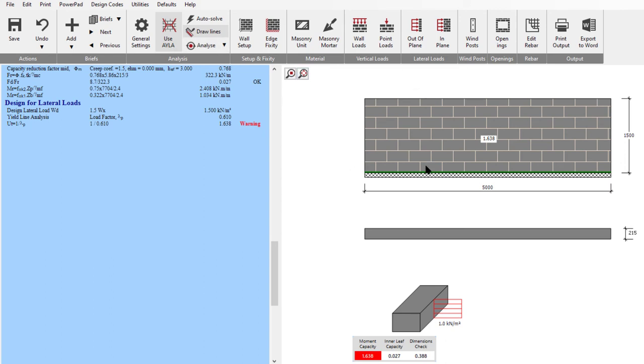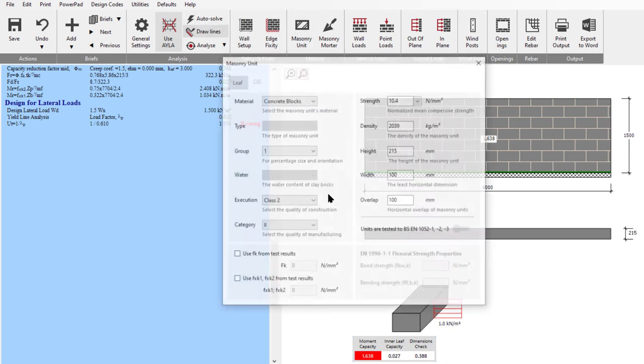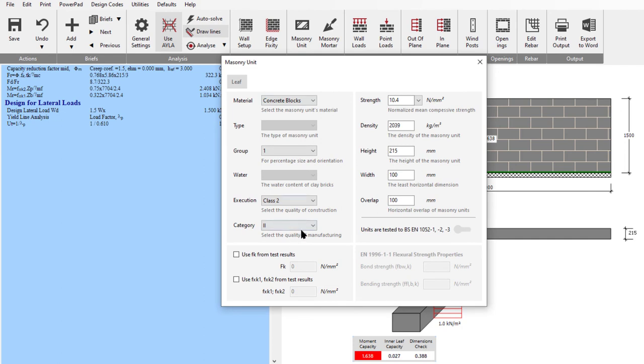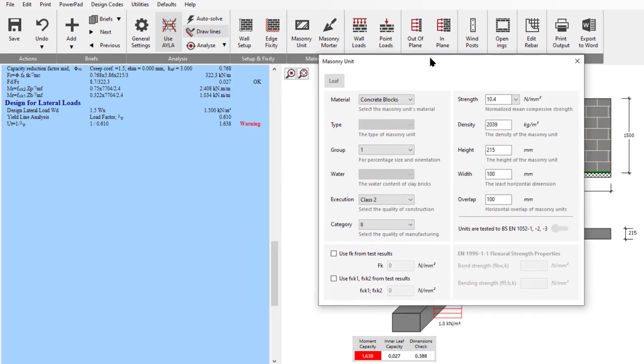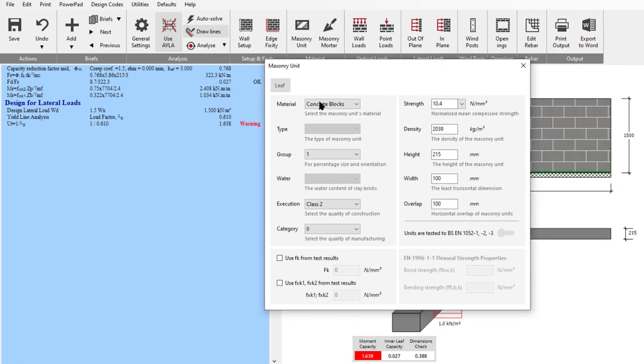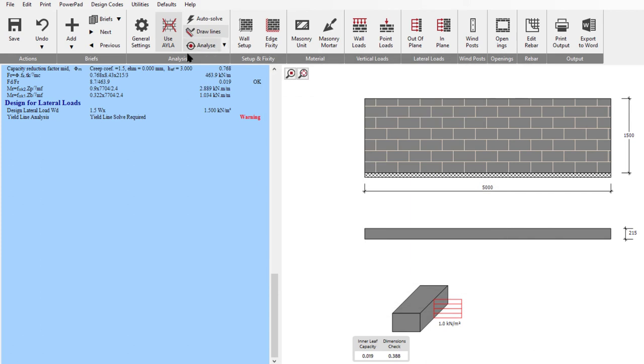What we can do is we can introduce piers, or we can thicken it. We can also, to a very limited extent, play with the masonry strength. It's concrete class 2 blocks and it's 10 newton blocks. So if we look at what our current ratio is, it's 0.1638. If I go all the way up to 17 newton, it's probably then going to recompute down slightly different, but very little. Nope, it's not giving any more strength. We've already hit that cusp, and there's no more flexural strength.